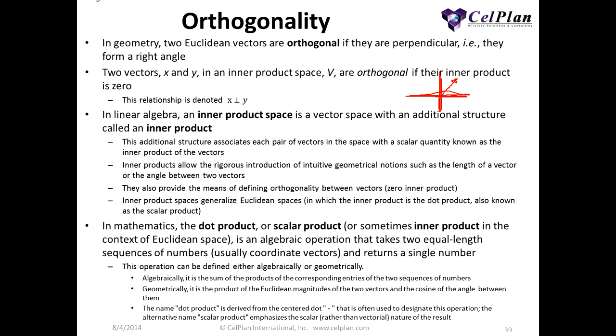But you can change the cosine and the sine will not move. So that's what is very important, that two waveforms are orthogonal, and this is the basis of OFDM.